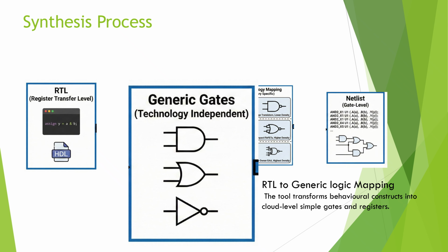At the same time, the tool starts logical optimizations. It removes redundant logic, shares common sub-expressions, and simplifies arithmetic where possible. So if I write neat and predictable RTL, the tool can see patterns and optimize them well. If my code is weird and inconsistent, it will generate weird and inconsistent hardware. That is absolutely true. Good coding style clearly helps the synthesis tool create better hardware.